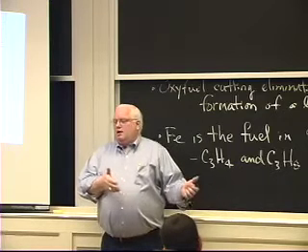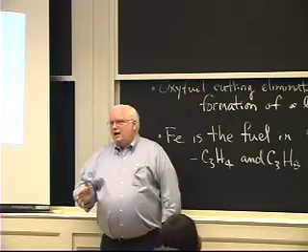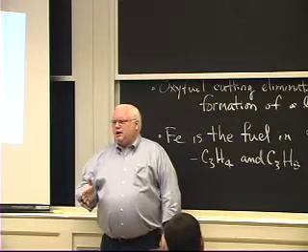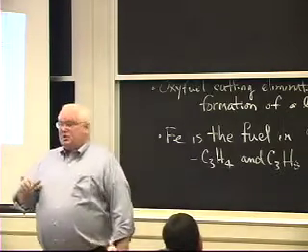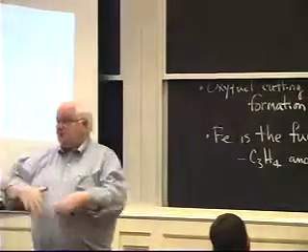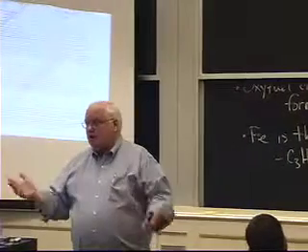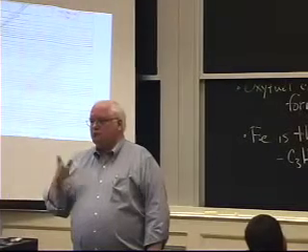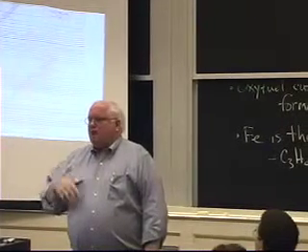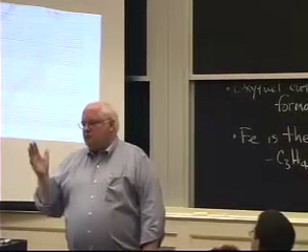Okay? We're nowhere near even giving you a headache in welding. Welders don't complain, oh, I got a headache, unless they've been welding in a confined space. In which case, it's not just carbon monoxide, it's the carbon dioxide. You're just excluding oxygen. They suffocate. Okay? Other questions? There are fumes and gases in welding, and people study these things.